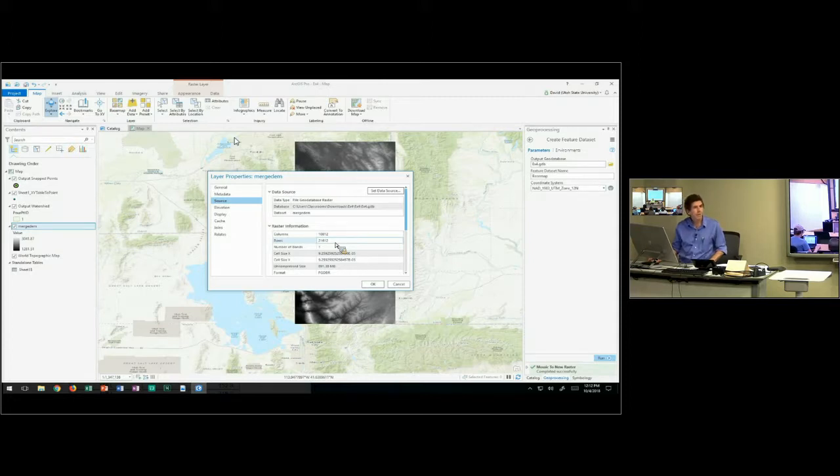What are the units here? Does anybody know what the units are? It's decimal degrees. So this is 0.0000409259 degrees. For the thing that I've asked you to turn in, the cell length in meters, I've said to assume the Earth is spherical, and I gave its radius. You can then go to the calculations we've done and do the north-south calculation, the east-west calculation, and then figure out the area as the product of those two.